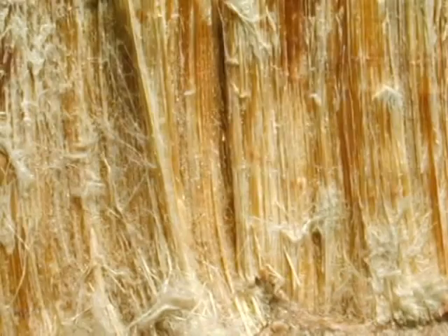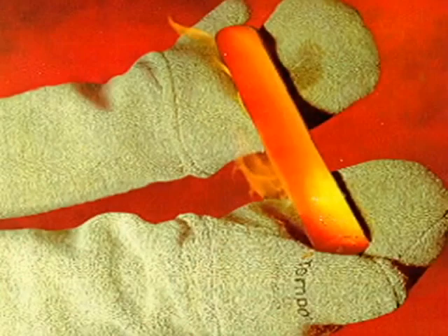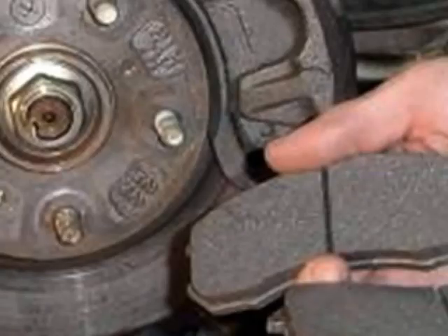Asbestos has and continues to be used in thousands of different materials such as flooring, ceiling texture, and plasters. Asbestos-containing materials in good condition, if left alone, should not pose a danger. However, if you're planning to renovate or disturb these materials, harmful cancer-causing fibers can be released into the air unless